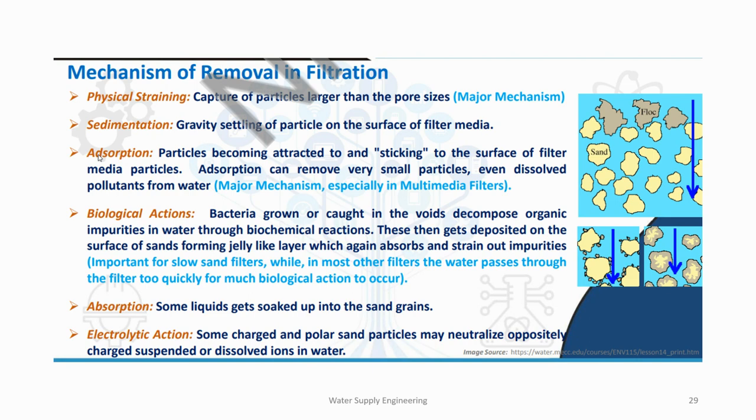And why biological action is possible in the case of slow sand filter is, here the filtration process or the movement of water is very slow, so the biological action is possible to happen. Now the fifth process, absorption. In the case of absorption, the liquid gets soaked up in the sand grains rather than sticking onto the surface of the particles.